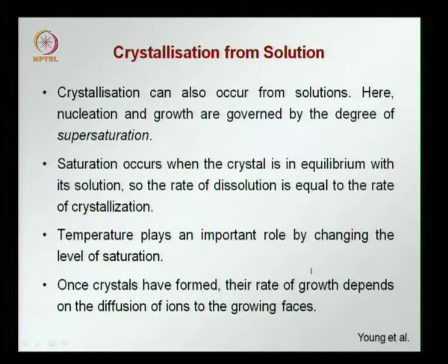Temperature changes the level of saturation. At higher temperatures more material can be dissolved, and therefore at a certain temperature you can have a different level of saturation than at another temperature. Once the crystal is formed, the rate of growth depends on the diffusion into the growing phases. So, once you have a nucleus occurring and a crystal growing, this crystal grows as a function of how much diffusion can occur in the growing phases.